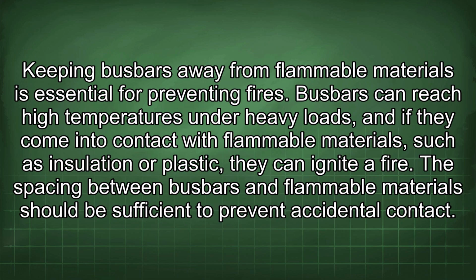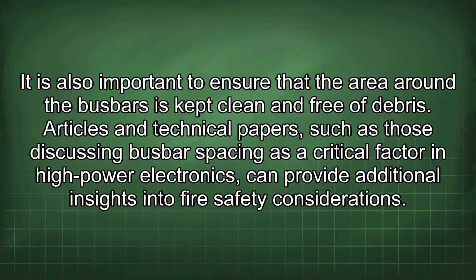Keeping busbars away from flammable materials is essential for preventing fires. Busbars can reach high temperatures under heavy loads, and if they come into contact with flammable materials, such as insulation or plastic, they can ignite a fire. The spacing between busbars and flammable material should be sufficient to prevent accidental contact. It is also important to ensure that the area around the busbars is kept clean and free of debris. Articles and technical papers, such as those discussing busbar spacing as a critical factor in high-power electronics, can provide additional insights into fire safety considerations.